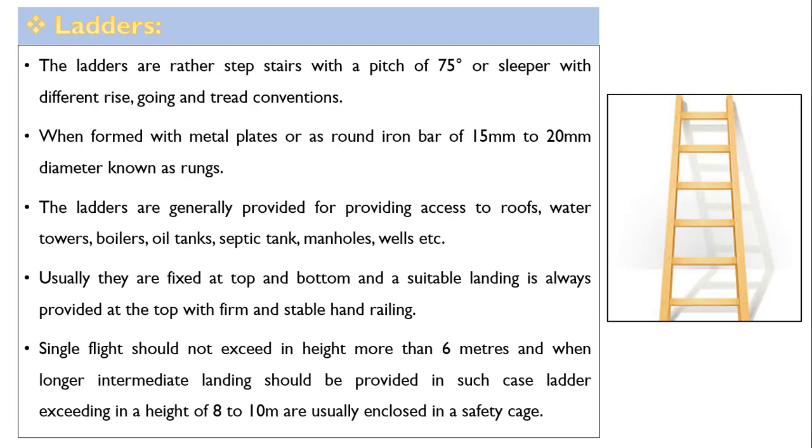Now coming to ladders. Ladders are rather steep with a pitch of 75 degree or steeper, with different rise, going and tread convention. In case of ladders, rise, going, all these things may be different. When formed with metal plates or round iron bars of 15 mm to 20 mm diameter, they are known as rungs. When formed with metal rungs, ladders are generally provided for access to roofs, water towers, boilers, oil tanks, septic tanks, manholes, wells, etc.